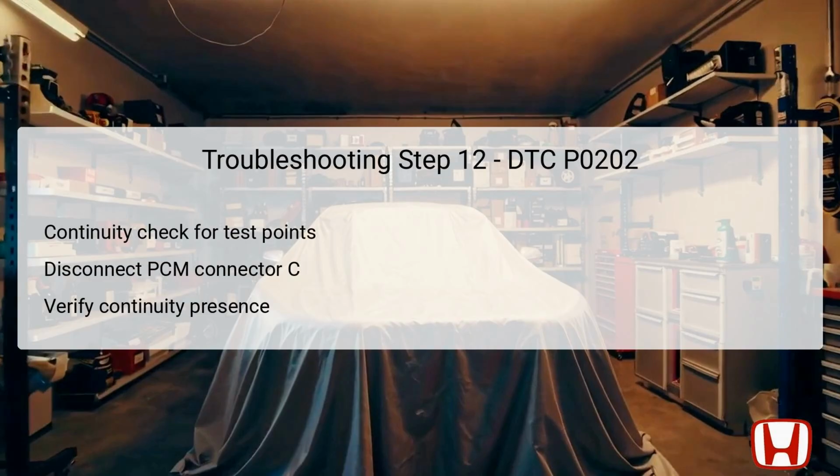If continuity is confirmed, there are errors elsewhere that require rectification. If no continuity is present, it indicates an open circuit in the INJ-F3 wire, which will need to be repaired to restore the circuit integrity. Conducting this continuity check is essential in isolating problems within the wiring harness.